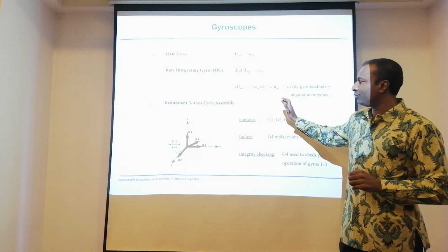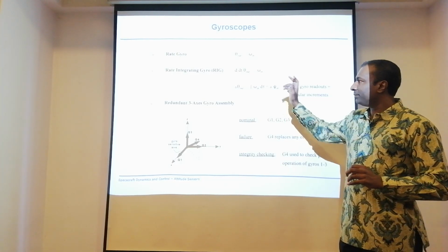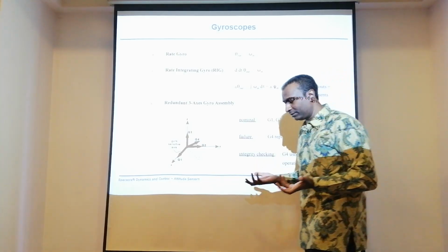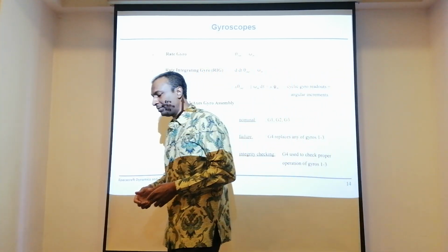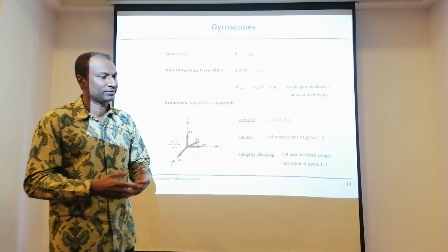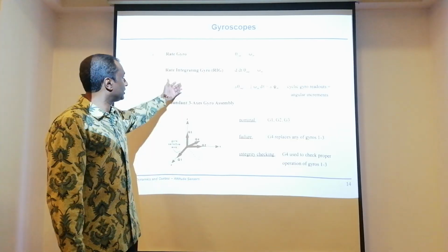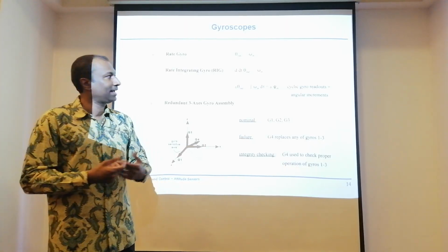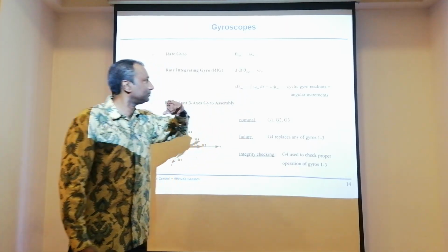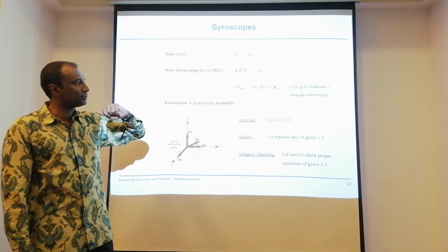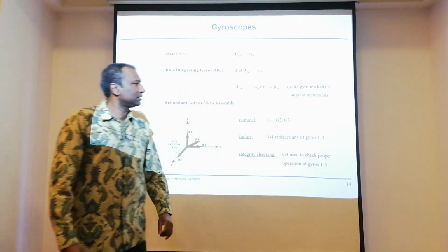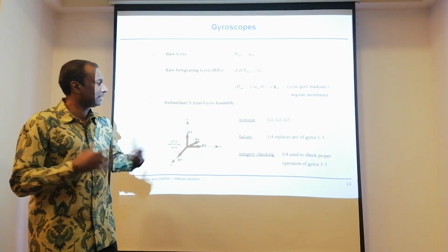Before we go into the fiber optic gyro, with mechanical gyros, when we actually run the gyro, the output will be angular velocity, but there is also something called an integrating gyro. And the integrating gyro gives you the exact attitude. So you integrate that angular velocity, and the readout would be the actual increment of the angle.